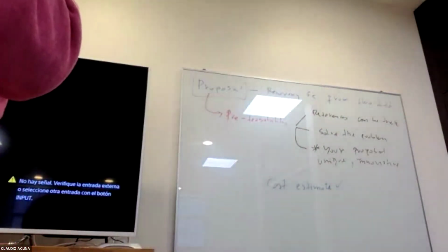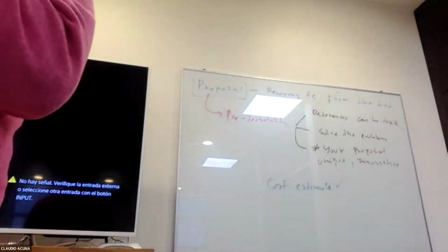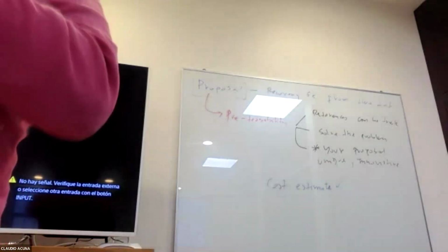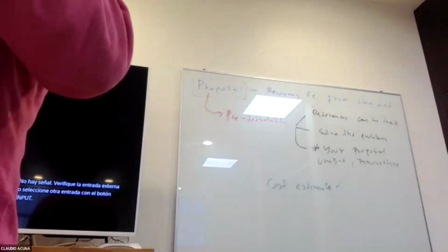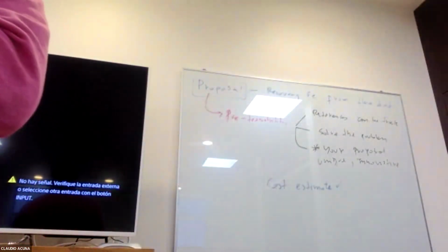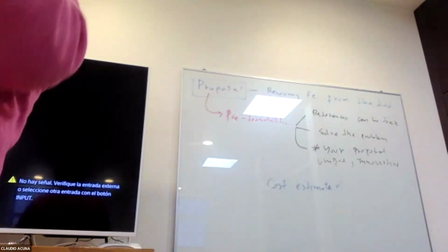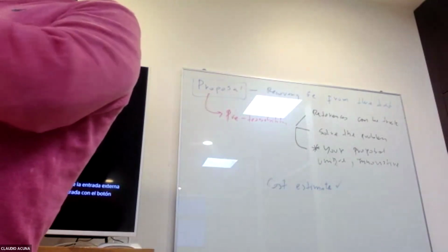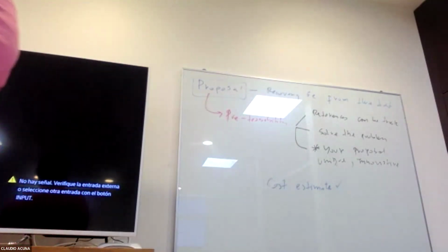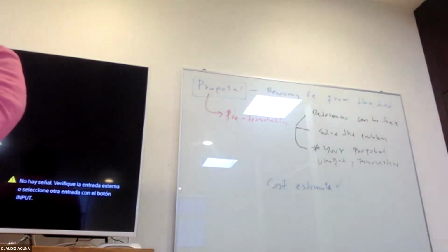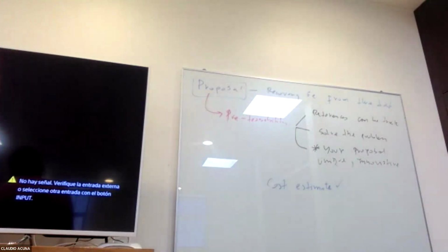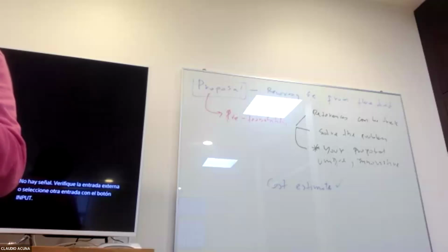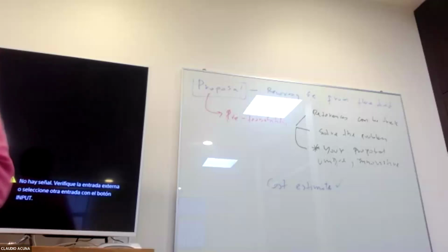Then you have selective extraction, and depending on the concentration, if it's very low, it will be ion exchange, membrane. If it's pretty high, say 5 grams per liter, 2 grams per liter, it would be solvent extraction. Okay, that would be selective extraction. And then once you have concentrated your product, 30 grams per liter, 50 grams per liter, you can go either electrowinning, precipitation, crystallization, and in between, of course, you have purification stages. We will see the case today, the zinc case.